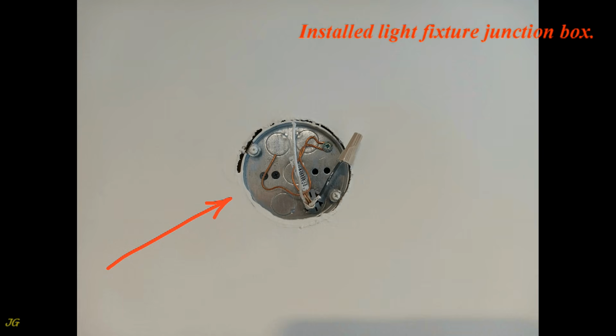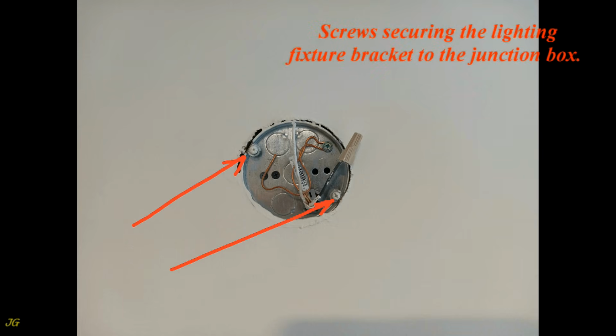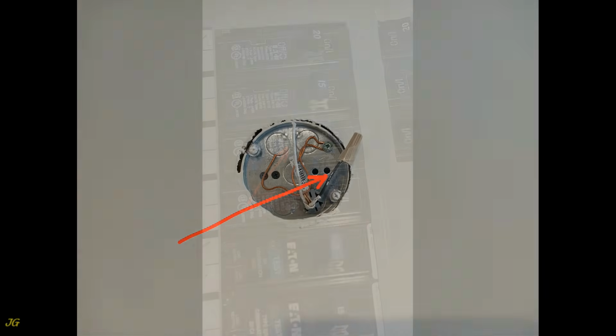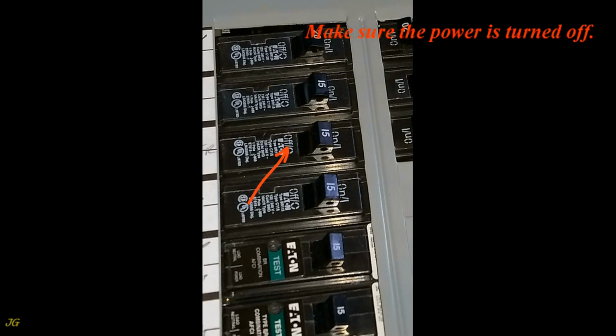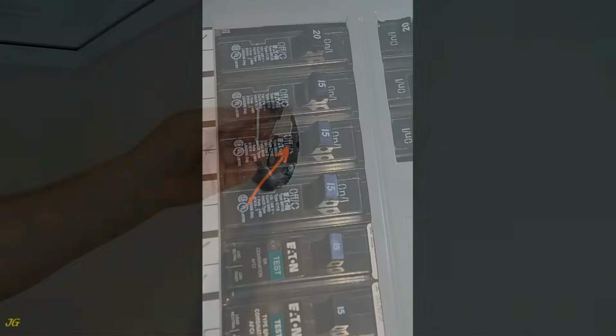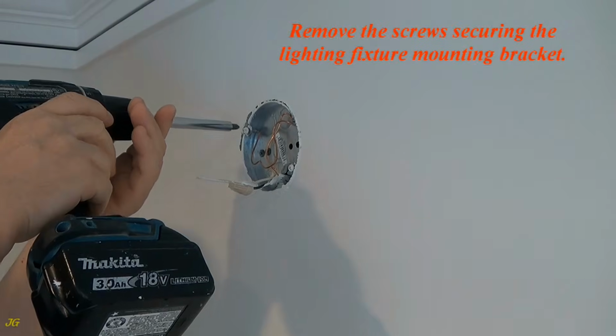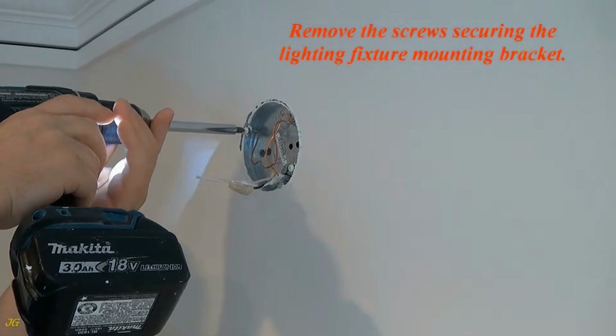Installed light fixture junction box. Screws securing the lighting fixture bracket to the junction box. Ground, bare wire. Neutral, white wire. Hot, black wire. Make sure the power is turned off. Remove the screws securing the lighting fixture mounting bracket.